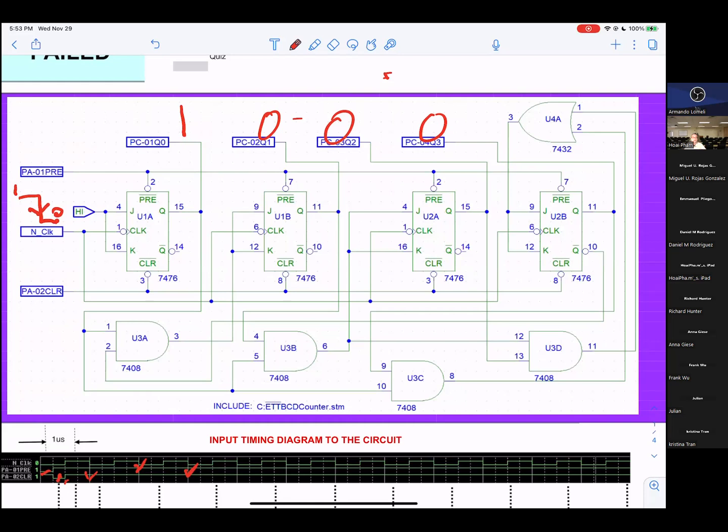And you have to use the oscilloscope to see U1 pin 1. You can see a square wave. That means the clock keeps going. So that will help a lot. You can check U1 pin 1, make sure you get a square wave. That means the clock. U2 pin 1, U2 pin 6 guarantee you get the clock.